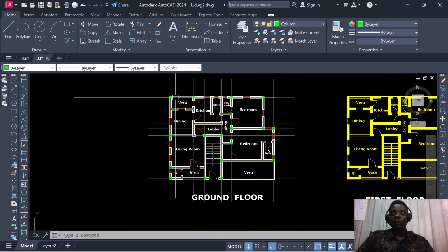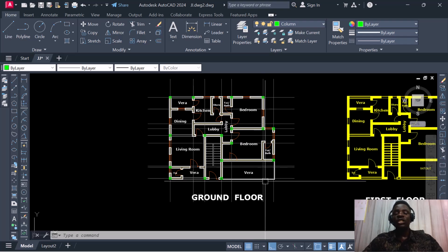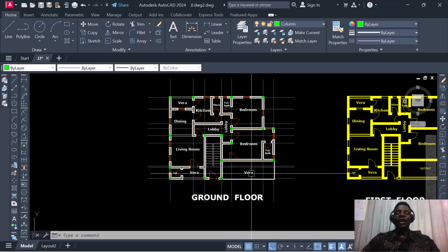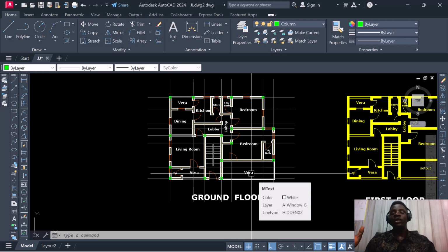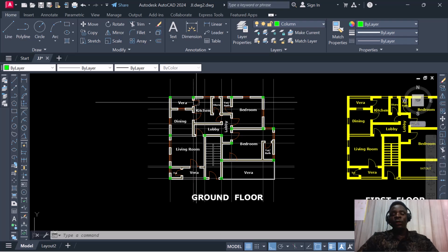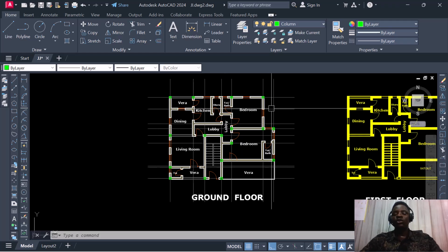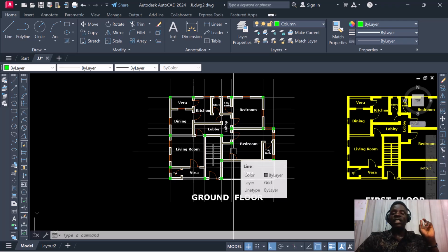So you can see we have achieved our GA, which is the first step. What you need to understand when you're carrying out your structural drawing is that a general arrangement consists of how you analyze where you arrange your beam according to how the structure is going to be, where you're going to have your slab, your beam, and your column. So you can see all this area where we need our slab, we introduce our beam as due, and where we need our column to support the stress generated from the building, all the other load, everything has been put into place.